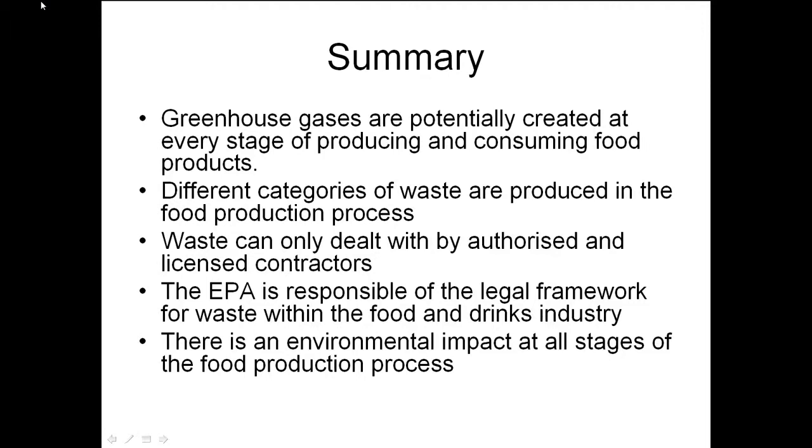Remember the sewage plant? You wouldn't know this, but I've worked there, so I had to deal with that. The way they clean up water is they've got bacteria in the water at the sewage plant, and they oxygenate the water to multiply these bacteria. The little bacteria eat up all the organic substances, and a byproduct is methane and sludge.